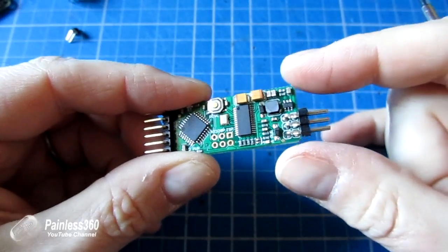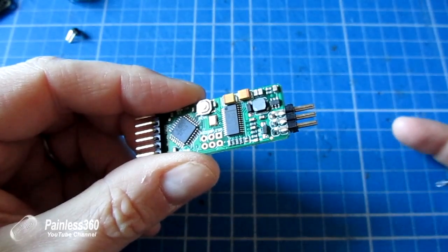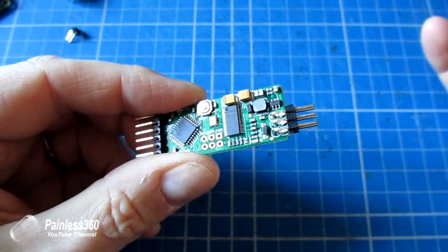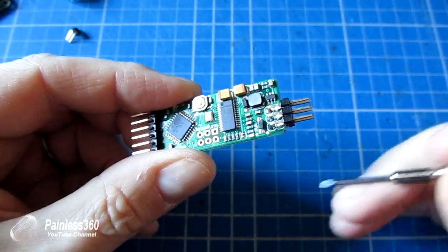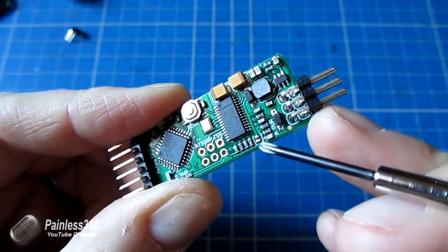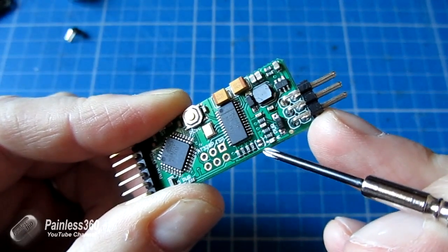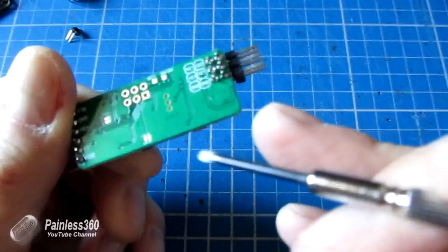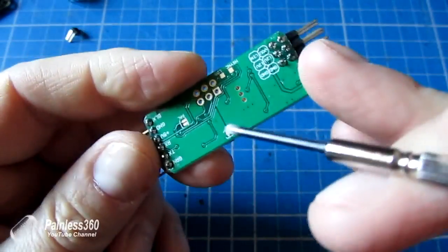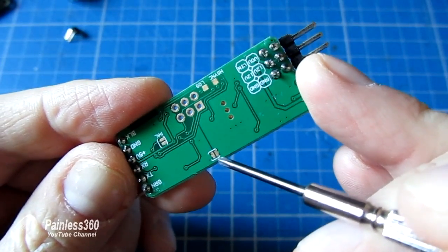So before we plug the board into the FTDI connector, we're going to bridge a couple of connectors. On a lot of the boards that I've ordered, these have already come pre-done. On this one, interestingly, it hasn't. And on the board, there are these two pads right here that have got separate little blobs of solder on. And on the back, there's another two pads here, which have got nothing on at all.